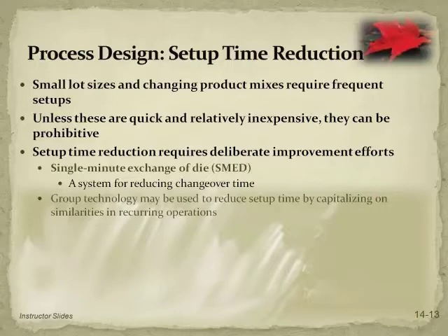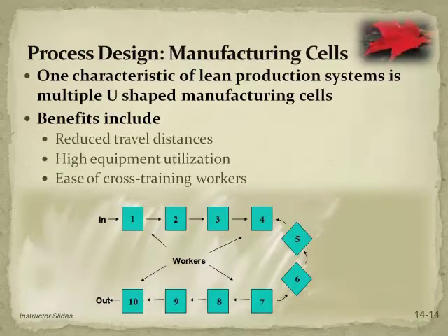So one of the techniques or methodologies for doing setup reduction, going through and reviewing all the steps in the setup, changeover, and eliminating the ones that we don't need to have, is called single minute exchange of die, or SMED.